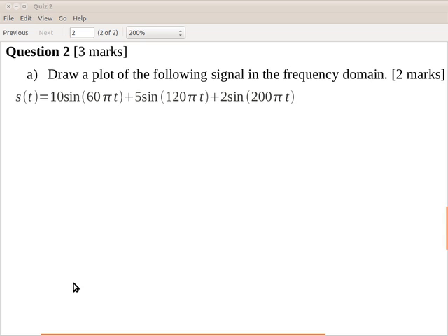Normally in real life, when we look at the next topic, we'll talk about different parts of the spectrum. To avoid interference, we transmit a signal with a particular bandwidth at some portion of the spectrum. If we transmit another signal at the same bandwidth, same portion of the spectrum, they will interfere with each other, and that causes problems. So normally our signal, if someone else is transmitting at the same time, needs to use another portion of the spectrum. And that's why bandwidth has some cost incurred.